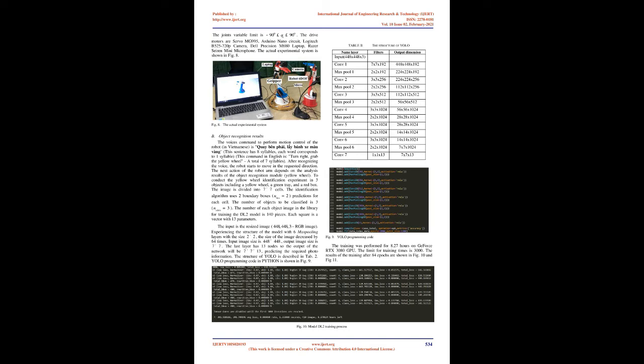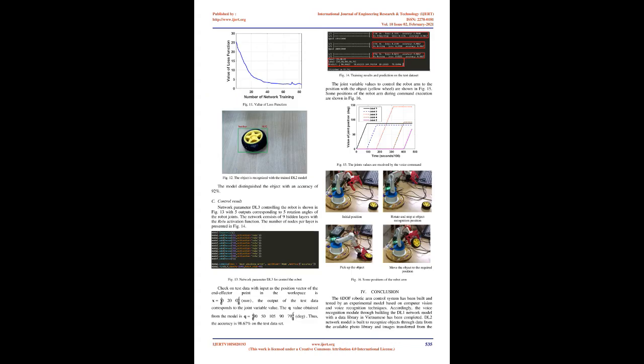An intersection over union (IOU) function is used to evaluate the predicted accuracy of the bounding box based on the labeled bounding box parameters, sample data. The larger the IOU, the better the evaluated model, well trained. The computed data for the DL3 network model is a spatial coordinate set and the corresponding set of rotation angle parameters that were collected and fed into the training DL network repeatedly until the model could give control signals for the robot accurately.